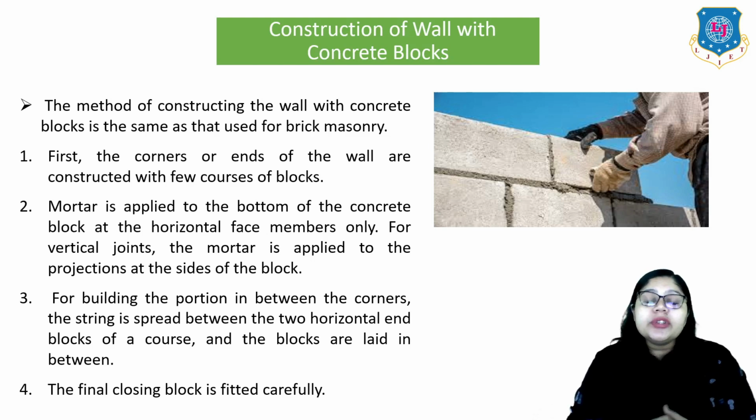For building the portion in between the corners, a string is stretched between the two horizontal end blocks of a course and the blocks are laid in between. The final closing block is fitted carefully.